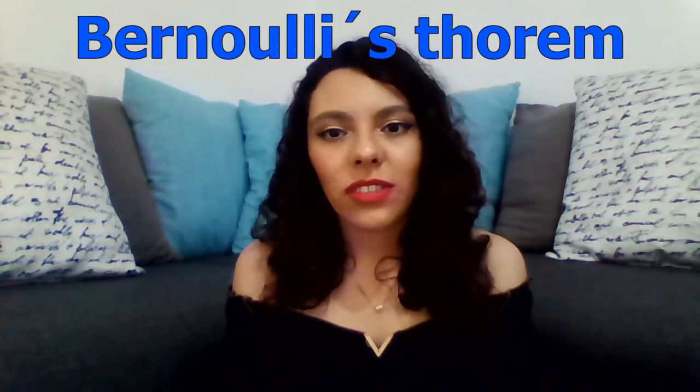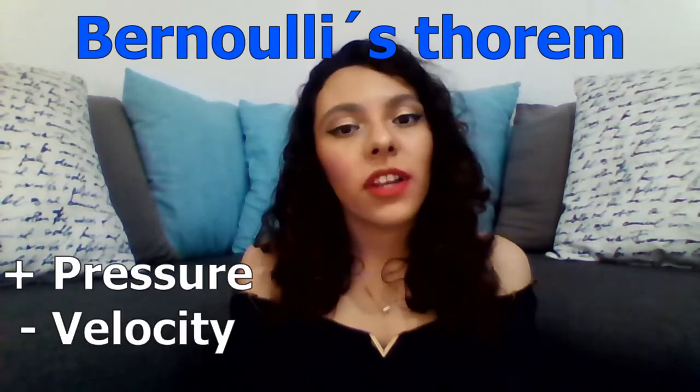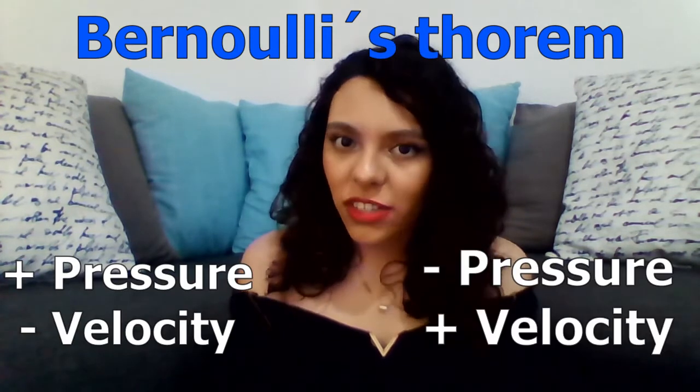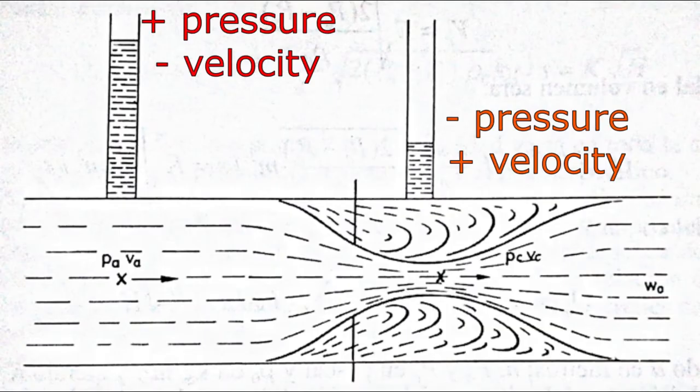along a horizontal line of flow, the higher pressure regions have a lower fluid velocity, and the lower pressure regions have a higher fluid velocity. Yes, I also found it confusing at first. As you can see here, we have a pipe with a reduction, and we can see that in the upstream tap there is more pressure than in the downstream tap. And this is exactly what Bernoulli's principle says, since the fluid velocity after the reduction is greater than that before it.